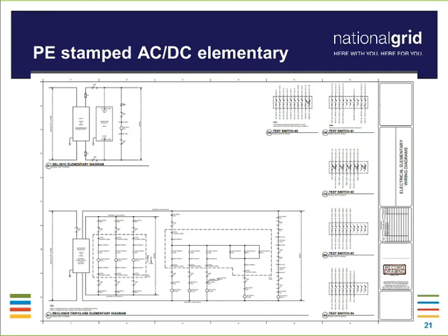A voltage test switch would be simply a test switch that opens. A current test switch would be something that you would not only need to open and isolate for testing, but anytime you open a current transformer, for instance, when it is connected to a primary conductor and current flow can still be induced on the CT, it would be very important to be able to shunt that test connection. So there are certain test switches for a current transformer that would need to shunt across the terminals so it doesn't overexcite and cause catastrophic failure of that instrument.